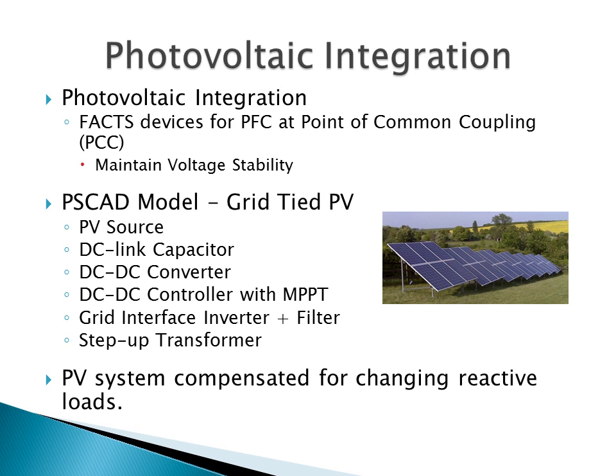The maximum power point is tracked by means of the incremental conductance algorithm because it is the point of maximum efficiency and output power in the PV system. In the study, several different load values were used to determine the ability of the PV to correct the power factor at the PCC. This design allowed the PV system to compensate for excessive reactive power at night and to supply reactive power during the day.